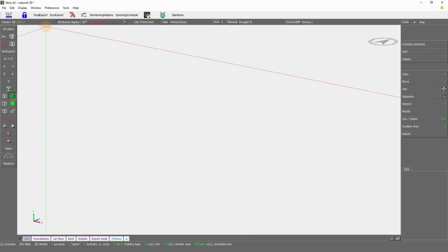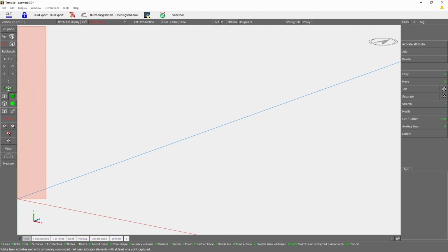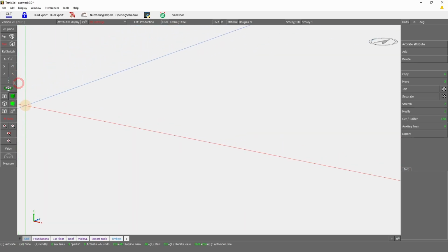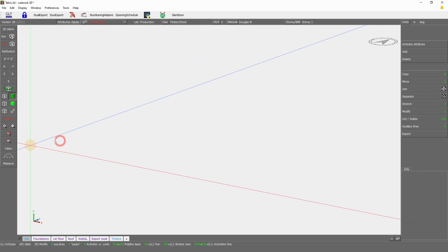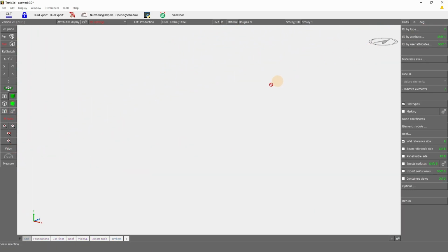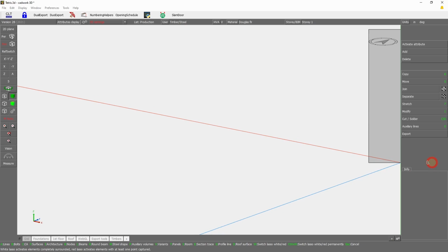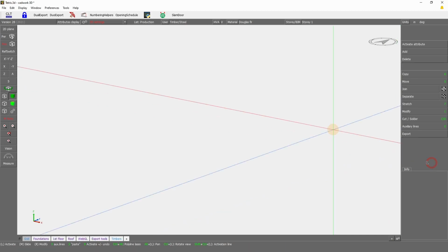bottom of your screen. Then about the interface itself, on the left side here is every function that changes the way you are looking at the model. So from the orientation of the views to the graphic representation to then what elements are being displayed, etc., etc. And here on the right side is basically the toolbox. So this is where you will find all the tools available to create new elements, change elements, modify them, cut them, basically transform what already exists, and also run your exports towards the 2D.